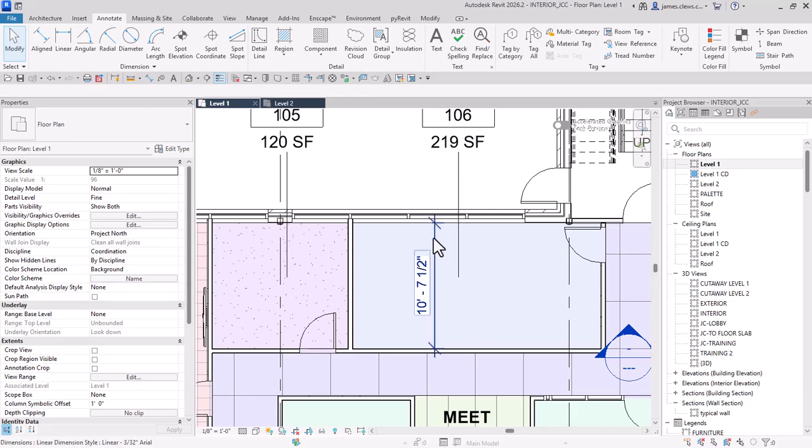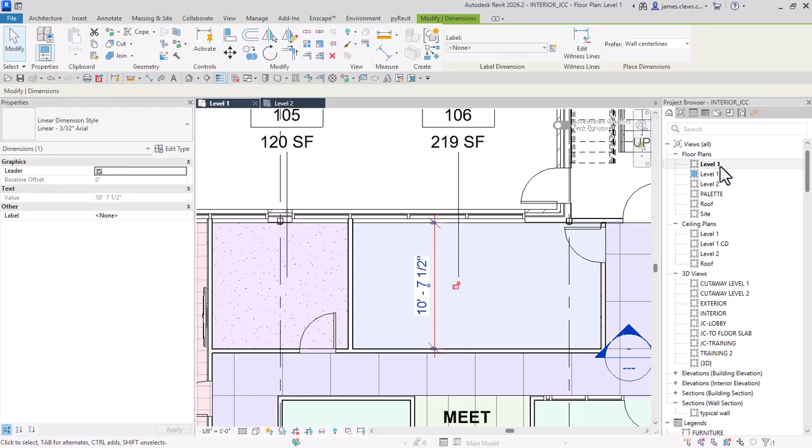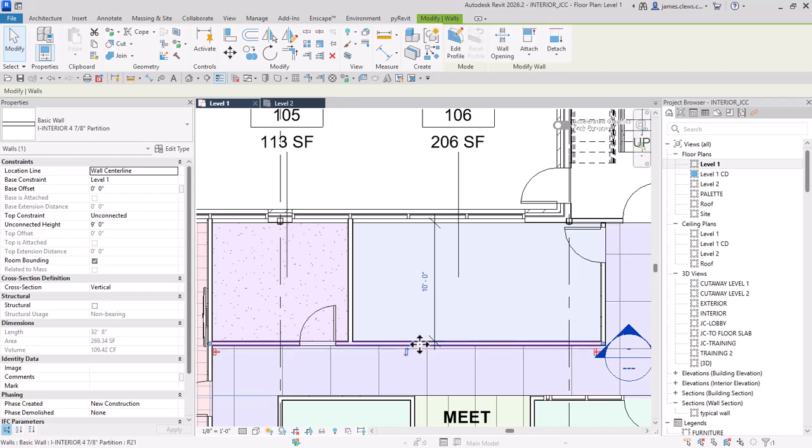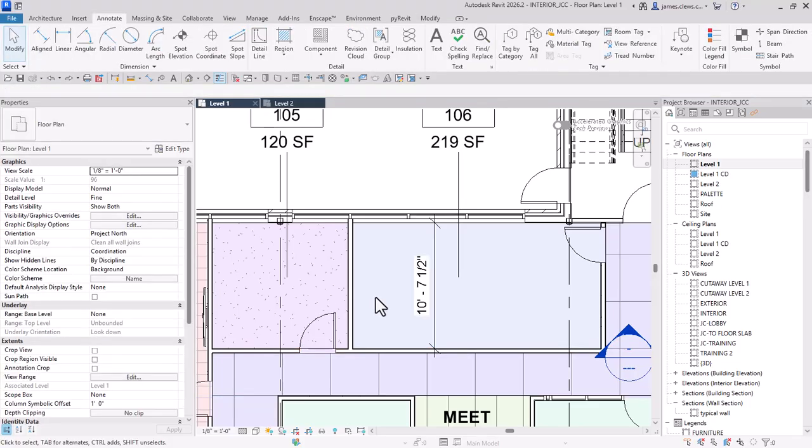When we were placing dimensions in the model, and we've been working on this level 1, the working view, or level 2, the working view, or the ceiling plans, not construction document views, but these. This is us driving the geometry, and the whole idea is that you can pick an object, choose the temporary dimension and change it. And in the absence of any other constraints, I could go in here and say, well, let's make it 10 feet and have the actual wall move and have the things on the wall moved. I'm going to do a Control-Z to go back.